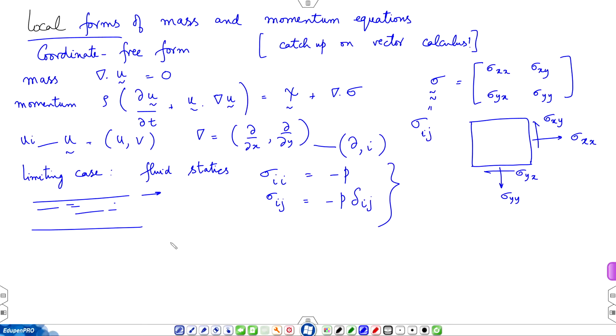Where we wrote F by A equal to mu u over h. So, if you consider a small element, now we are specializing Newton's parallel plate experiment all the way to the element level.